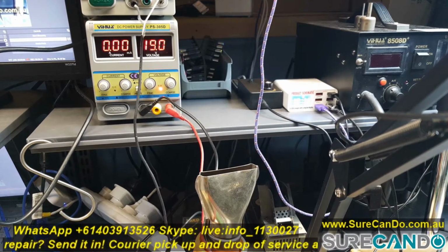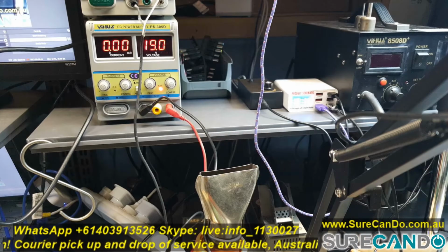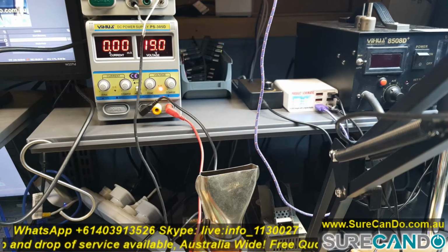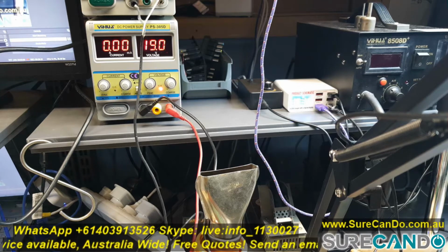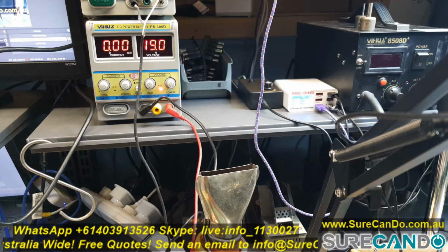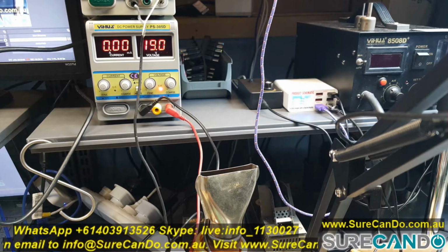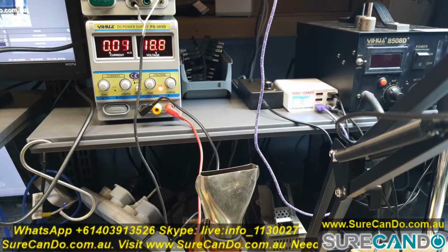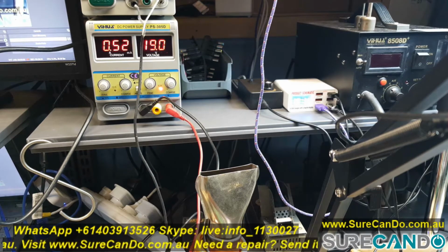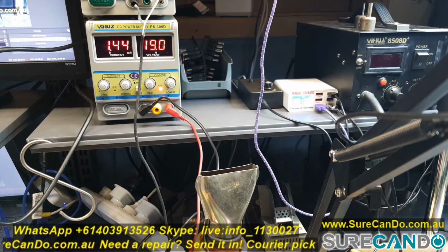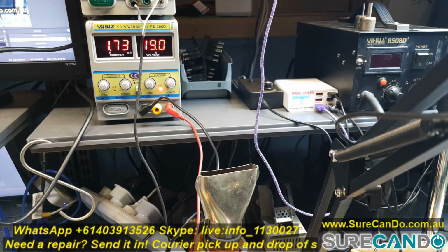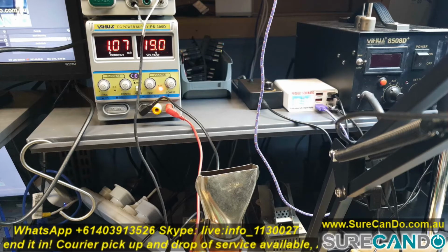So as you can see, I've removed the positive terminal. And when I reconnected, not killing myself, it's 19 volts, which is what's coming out of the power supply. Here we go, it's booting up, 0.4, pulling more amps, 1.3, 1.8, oh, here we go. And when there is no signal, you can't detect the signal, eventually the backlight goes off, and we're back to 0.4. So the behavior is all normal, so I don't think there is any component failure here.